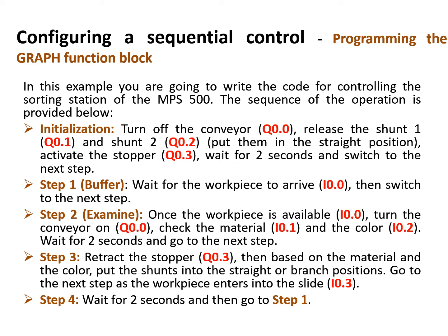So, what is this sensor? I0.3. This is a retroreflective optoelectric sensor, and that sensor will sense if the part has already slid into the slides.